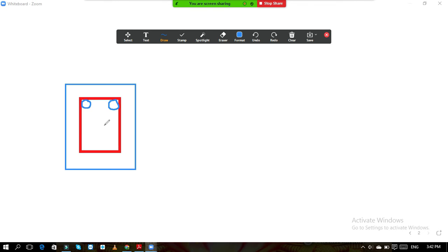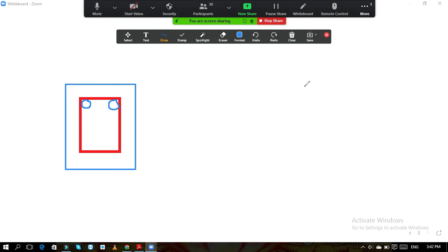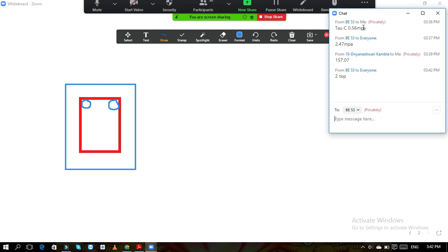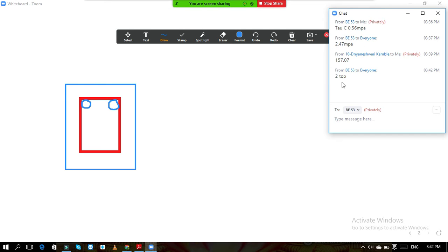So let me know how many bars are provided at the top and how many at the bottom, and the diameter of the bars. It is 2 bars at top, of 10 mm. And at bottom, number of bars and diameter?